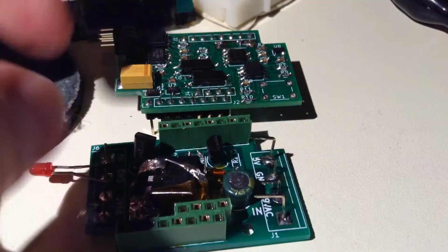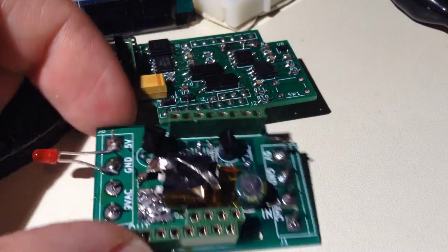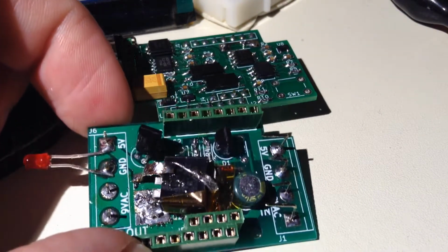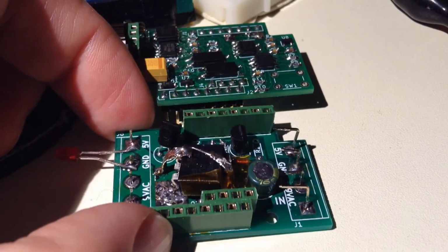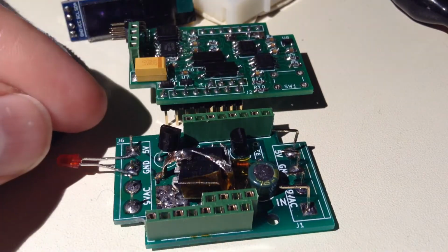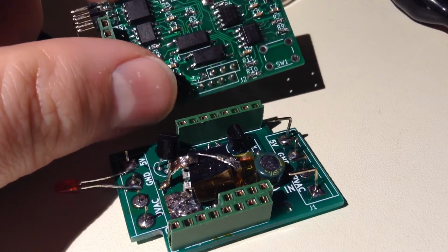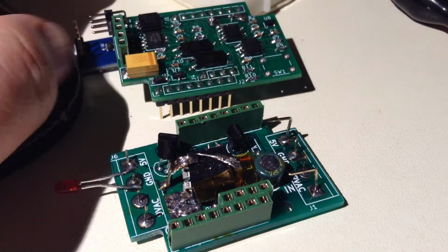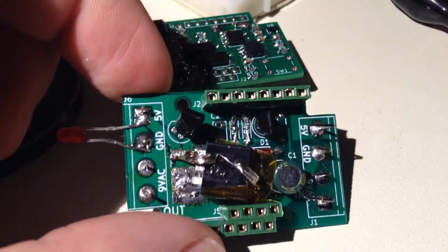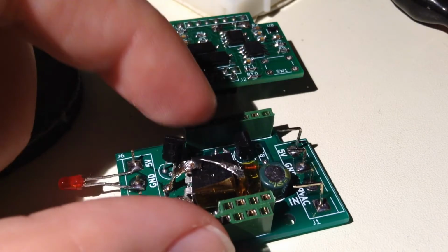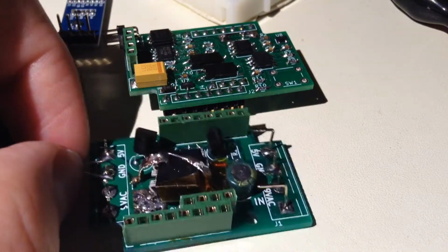The idea that I'm not using the microcontroller for everything is that the baseboard is doing the main function of saving the Commodore 64. So even though the microcontroller breaks down or doesn't run anymore, something happens to the oscillator or anything, you still have protection, because this device, this TL431, will still operate.